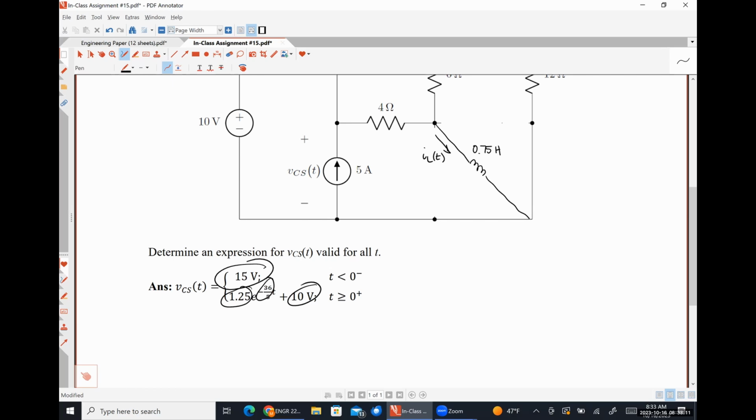This is an oscilloscope probe. It also has a BNC connector on one end, but it looks significantly different than the other one. This one is encased in plastic. This bit right here slides down, leaving behind a hook, and then this bit right here is going to be your ground connection.